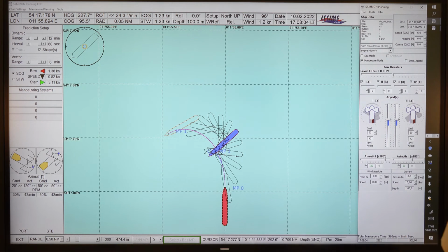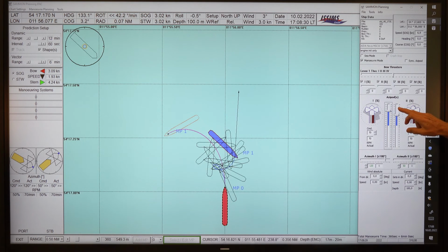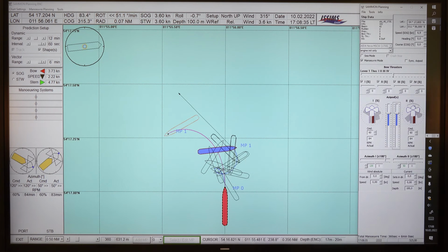For this reason, we could use a kick turn. For the time being, we are moving with 30% of engine order, but when we blow it up, for instance like this, maybe to 50 or 60%. So this is now 60% on both engines.